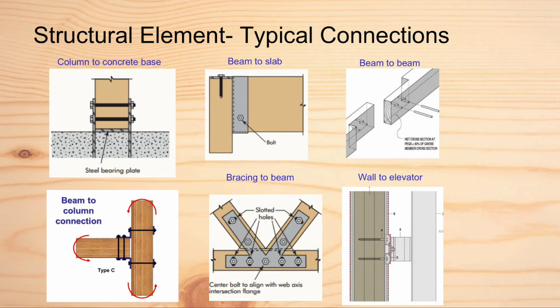Bolts, coach screws, and timber connectors have higher capacity than nails and screws. Therefore, bolts are most suitable for this residential timber structure, which large loads are imposed. It is used for connection of beams to other elements, such as column, slabs, and bracing.